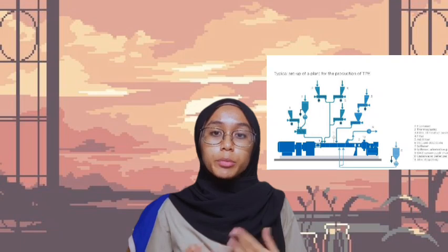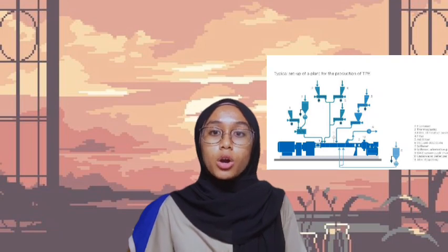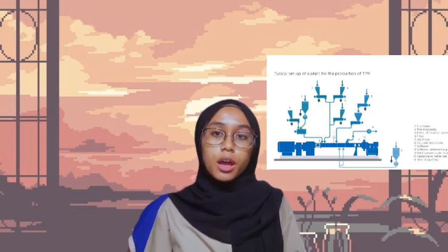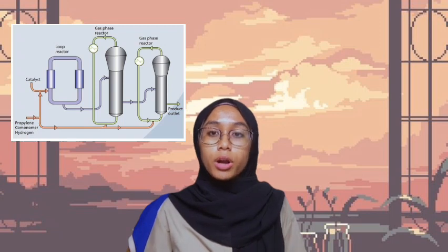Thermoplastic vulcanizates are prepared by melt mixing the elastomer and thermoplastic in an internal mixer or in a twin screw extruder. In the second step, vulcanizing agents such as cross-linkers or curatives are applied after a well-mixed mixture has formed. As the mixing process continues, vulcanization of the rubber polymer occurs under circumstances of high shear and high temperature.